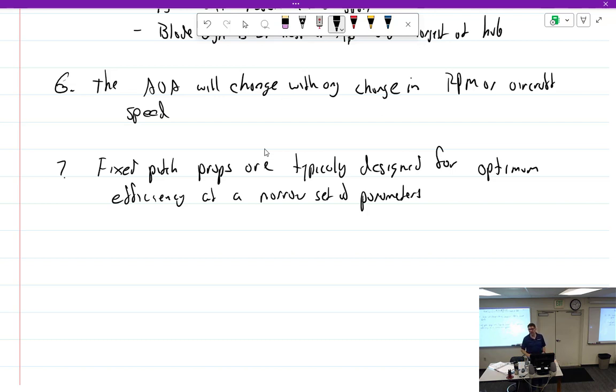Now, how did they design it to do just that? They didn't. As a mechanic, you set the low pitch stops to let it overspeed. They do that at the prop shop, and then you set the governor, which we'll talk about coming up, to stop it right there. So the governor senses the speed and changes the blade angle to stop it at that red line. Are you also looking at your manifold pressure to see the load on it too? Yeah, that you can do, because you won't do static RPM, but you can look at manifold pressure. But they don't give you that number, and if it's all the way forward, the manifold pressure is kind of set.